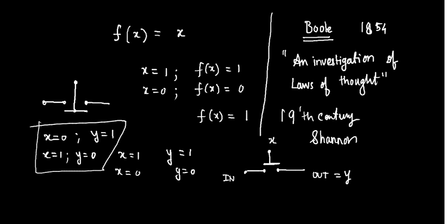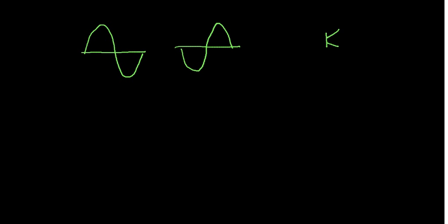In common emitter, you see that. Oh, how are you, all the hard work gone to waste. See, when there was such an operation, if you give an input like this, the output will be like this, a 180 degree phase shift in common emitter. That's why there is a minus sign, minus A, minus gm R_D, the voltage gain, current gain. Did you forget everything? So this is a transistor. Why was it a minus sign? Now it is common emitter.